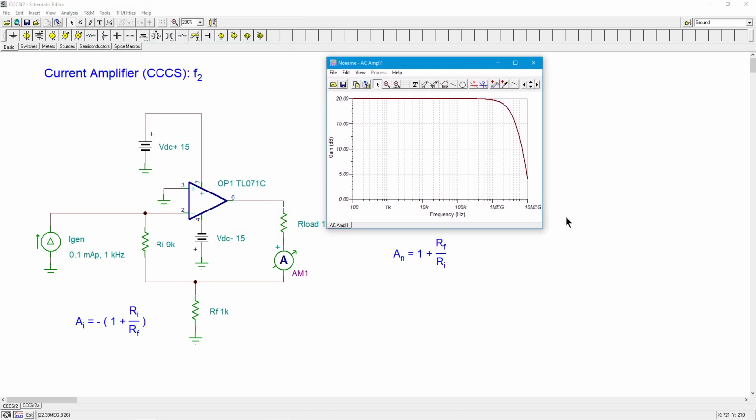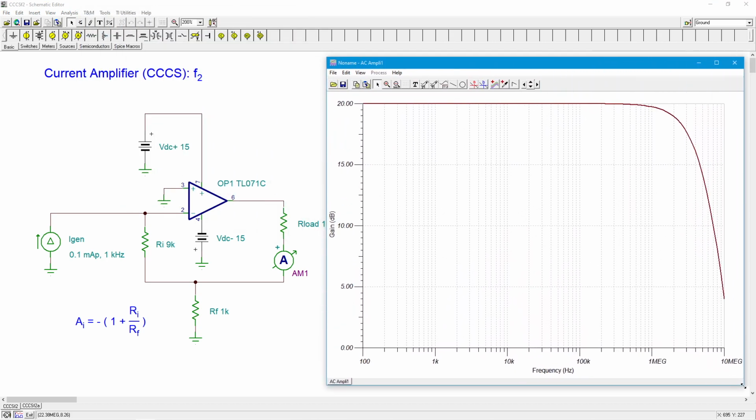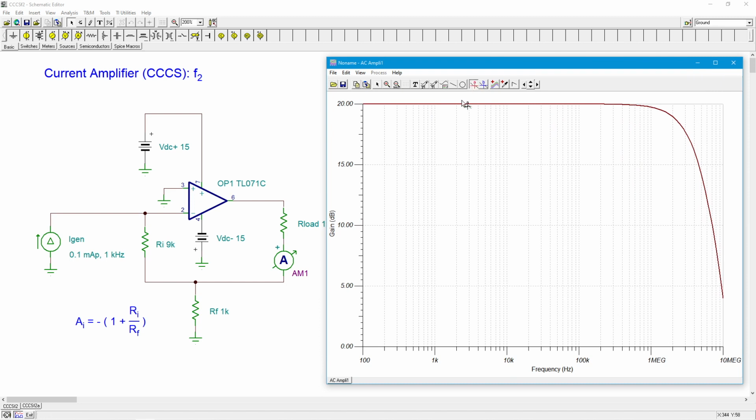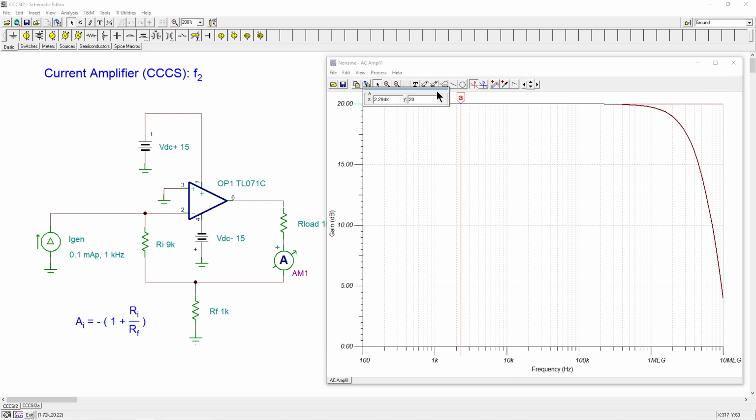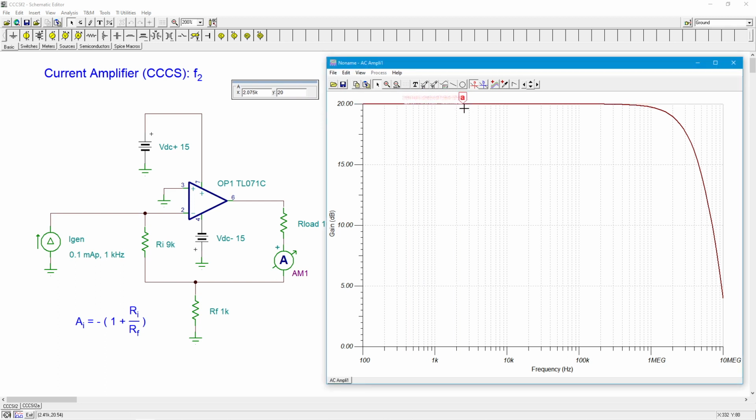Bring this over. Open it up so we can get some accuracy. The first thing I notice is the gain, right? The gain on this, like we said, is 10 or 20 dB. So that's what we're seeing right here. Down here in the pass band, we're getting 20 dB, looking good. So I'm going to have to go up to a 3 dB down point, in other words, where it hits 17. Okay, we'll call that 17, right? We're getting 3.475. Call it 3.5 megahertz.